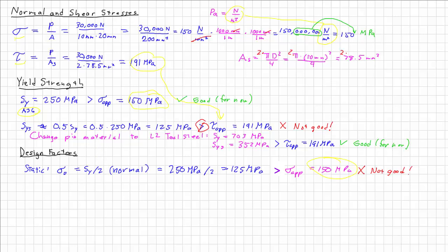So let's rearrange our equation there. The yield strength of our material has to be greater than 2 times our applied stress.